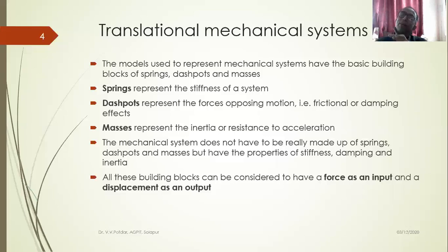So that lubricated joint can be modeled by using a dashpot, isn't it? I can always have a dashpot proper in a given system, but in some systems there will not be a dashpot proper, but dashpot-like behavior will be there, right? The lubricated parts, particularly grease-lubricated and oil-lubricated parts, they're damping the frictional motion, so they are dashpot-like elements.